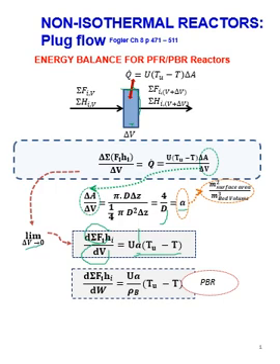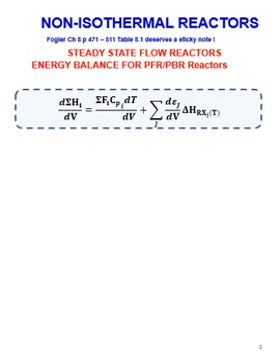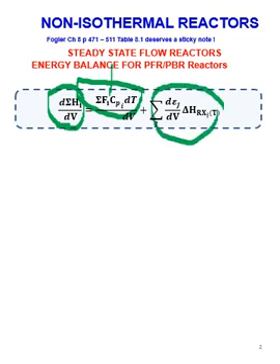If I want to write that energy balance for a packed bed reactor, where I want to use mass as my independent variable, make sure that you can see why you then need to divide that term by the bed density in your reactor. So once again, the enthalpy of my flowing streams, the total enthalpy, will change due to two effects. There's a change in temperature, where I consider the molar flow rate to be constant in that slice when I change the temperature, and it is going to change because there is a change in the composition, and that is accounted for by the heat of reaction.